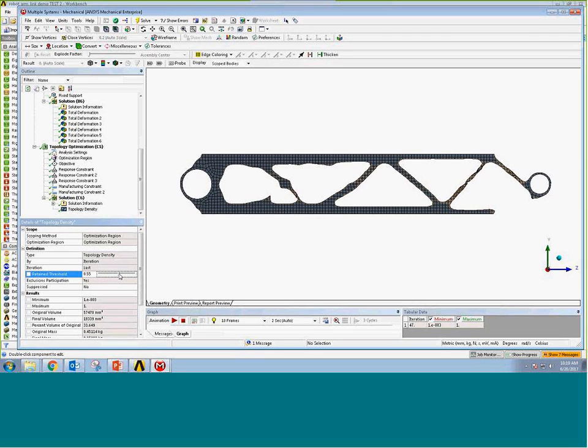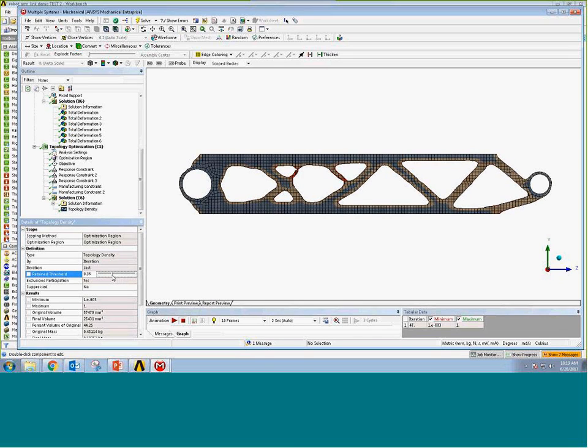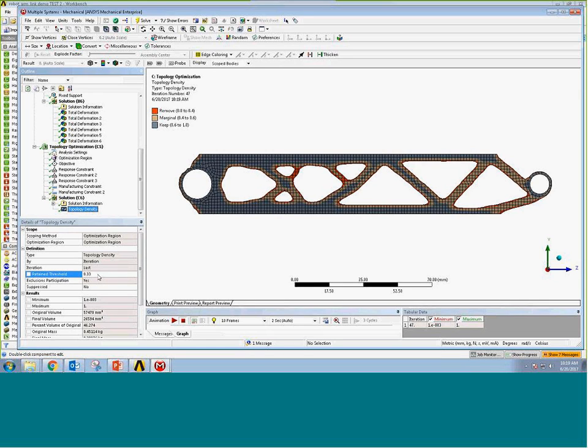So I can tell right away that this is not going to be a viable design. I need to go to a lower, more conservative structure. So around here might be a viable design. In my case, I'm going to go down to about 0.33, and that represents a more conservative design. Okay. Now, this is showing the distribution of material.